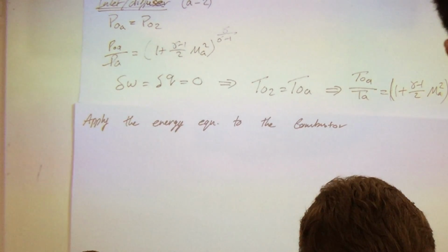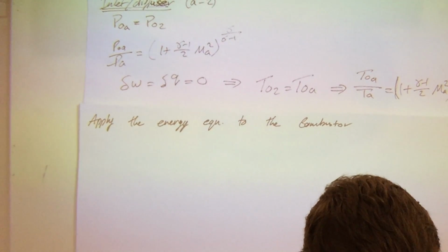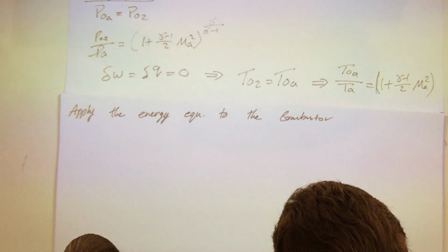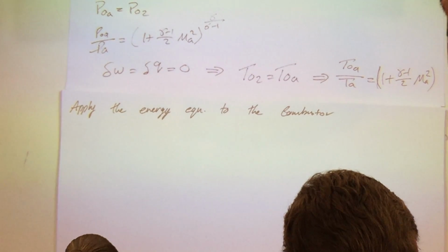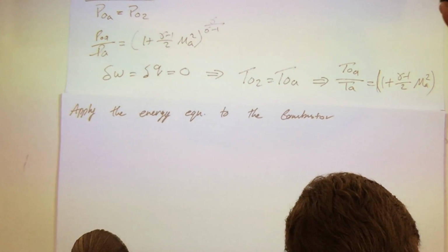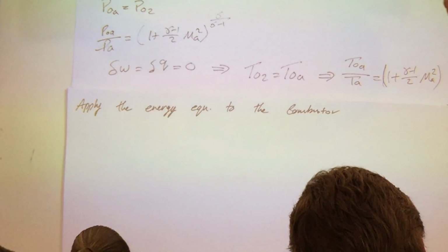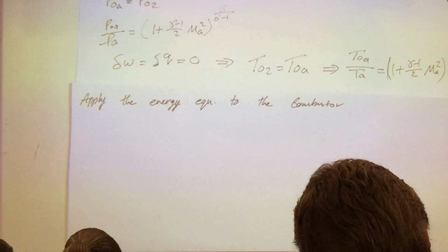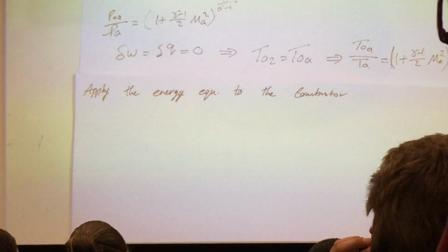Just to recap, I'm going to split it the same fashion as we did in the past. We started first by getting the heat of combustion, and then we used that to determine the adiabatic flame temperature. Why is the adiabatic flame temperature very critical for us? Because it is the Tmax that you have in the engine, and Tmax controls everything, the thrust, everything. So you first start with the heat of combustion, define the heat of combustion equation, then derive the energy for the gas expansion.